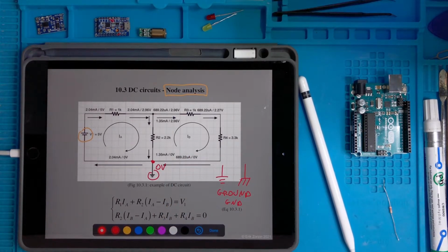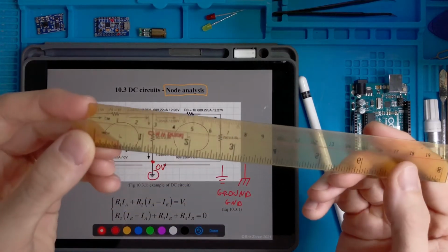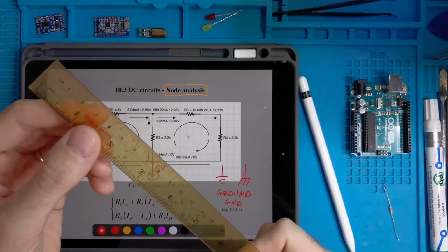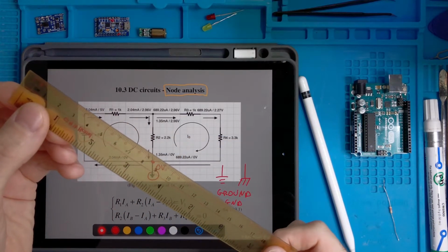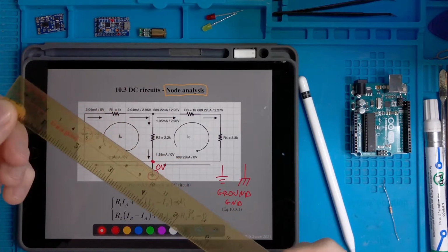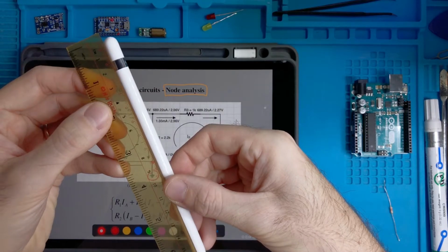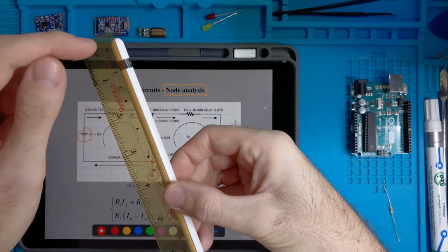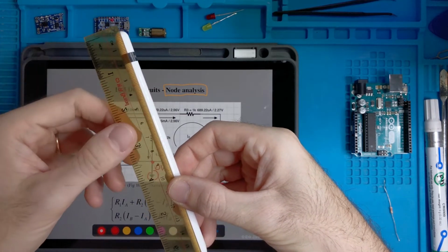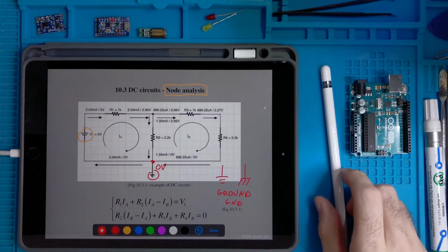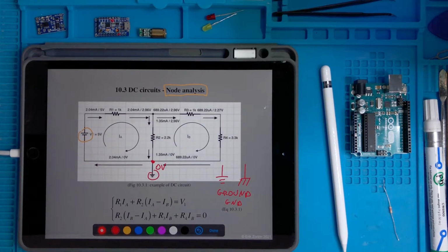It's like when you want to measure a distance with a ruler, a distance from one point to another, like the length of this pen, for instance, we define this to be our 0. The same thing happens with voltages. We have to define which is our 0. It can be any node, but we have to say which one it is.